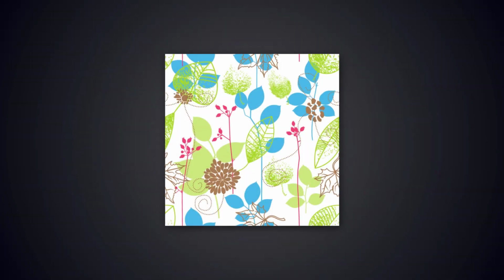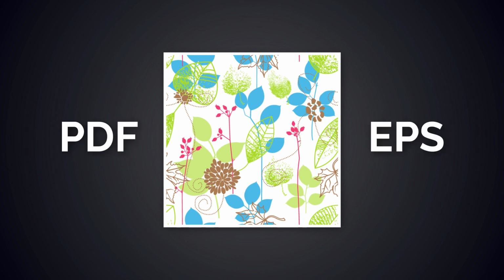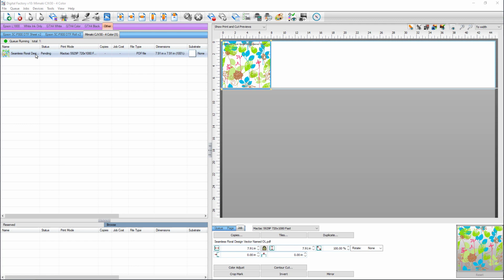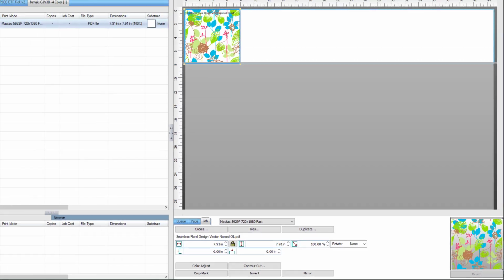Be aware that some design packages create a little white space around designs when files are saved as PDF or EPS formats. You want to make sure this is not the case. If there is a white line around the design, you could use the Tiles button on the Job tab in the status panel and crop the design before performing the step and repeat.